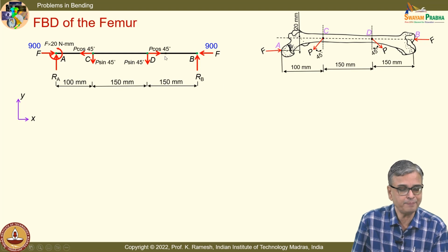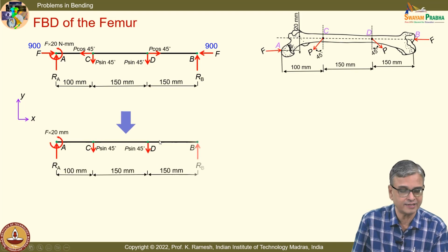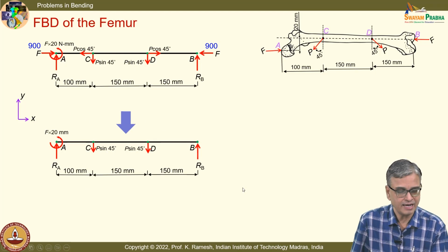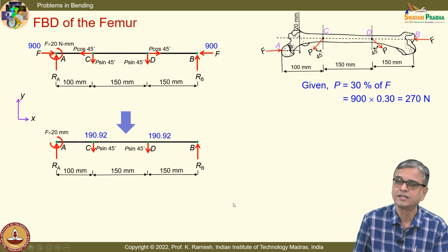I can replace this as the addition of 2 sub-problems, because we are living in linear elasticity. One is causing bending moment, the other one causing only axial compression.